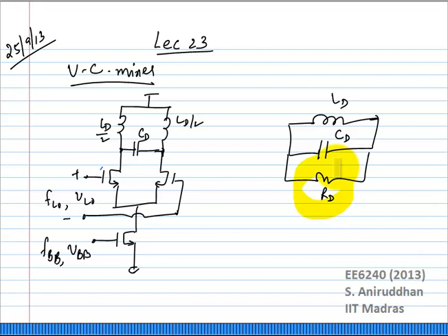That physical resistor produces noise, and I have already mentioned this before. You can show that the overall noise produced by this is the same as if you had a resistor RD. If the output impedance is RD at the frequency of interest, the noise produced will be the same as that produced by a real resistor RD. So far as load goes, it's very straightforward.